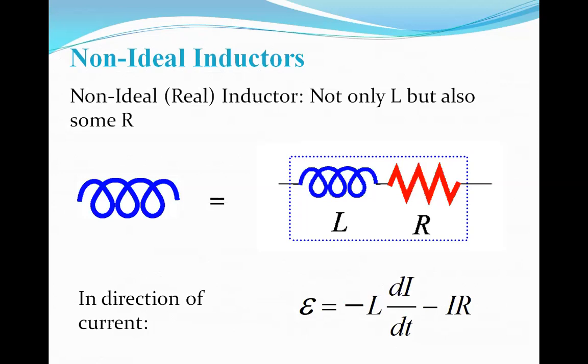It means it is in series with the inductance. So here we can see that this is an inductance and this is a resistance, which is produced because it is opposing the growth of current in the circuit, isn't it? This resistance can be called a reactance, because this resistance is produced due to an inductance. So the resistance produced due to the inductance is called inductive reactance.